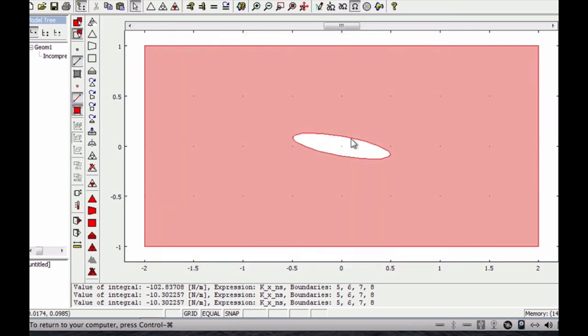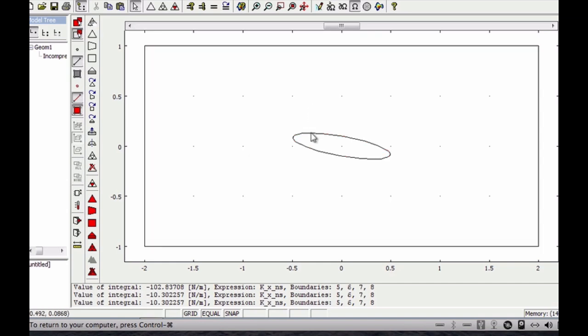The other boundary condition we didn't mention is that on this boundary, we put a zero velocity boundary. So basically a sticky boundary condition. It's called a no-slip boundary condition, which means that any air particle that hits this wall is stuck there and goes at zero velocity. But as you get further away from this airfoil, the velocity increases until it gets back to the ambient conditions further away. So that's what we're going to run it for.